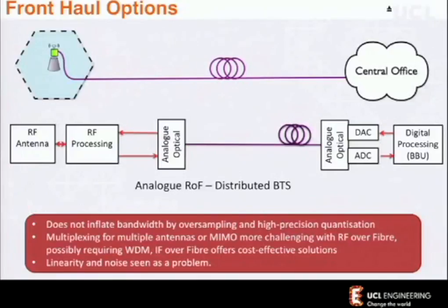But here, you've got 100 meg. If you want to take a 100 megahertz channel, 200 megahertz channel, pick that whole channel off that may have multiple users, multiple carriers in it, I could pick that all up and transport that all back with relatively straightforward optics. And actually move even more of my processing, the digitization stage, further back into the network.